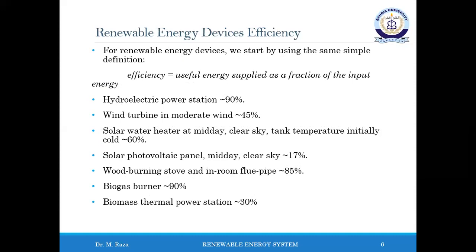It is more important to assess the actual production of particular devices at a specified site. Moreover, the environmental inputs are very variable. So the inputs are best averaged over time, usually a year. We need parameters that allow the annual production of a device to be assessed at a particular site, for which the term capacity factor or full load hours is used.